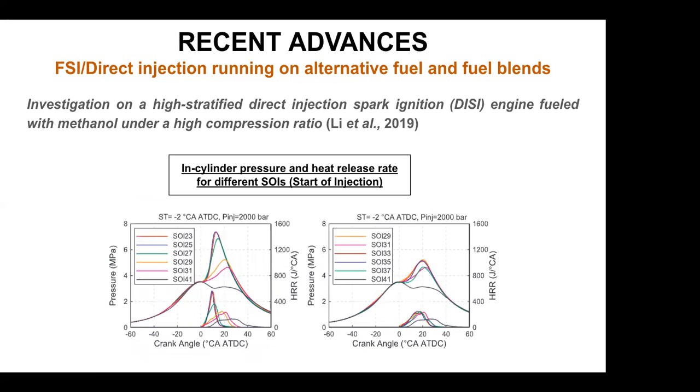Next. The result is this numerical model, which is used to investigate the combustion characteristics of the methanol engine at different operating conditions. First, the effect of SOI, or start of injection, on the combustion process of the methanol engine is studied. As seen in the figure, the combustion process is highly sensitive to the variation of the start of injection. Generally, the peak pressure gradually decreases with advanced SOI.